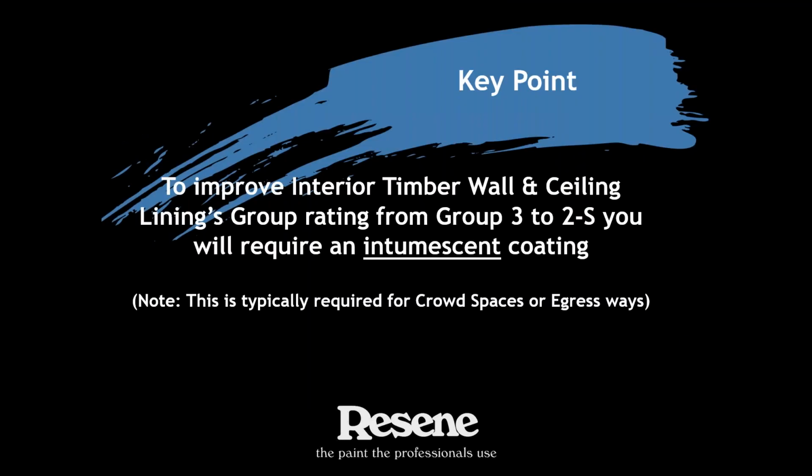A little note here on interior timber wall and ceiling linings. Obviously, we've changed now, and often for crowd spaces and egress ways, you need to improve the group rating from Group 3 to Group 2. To do this, you do require an intumescent coating. Standard paint coatings will not improve the group rating of your substrate.